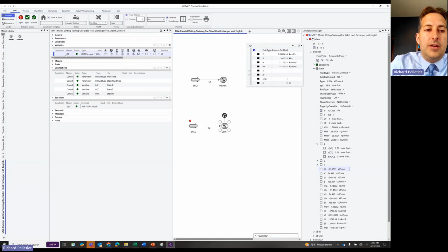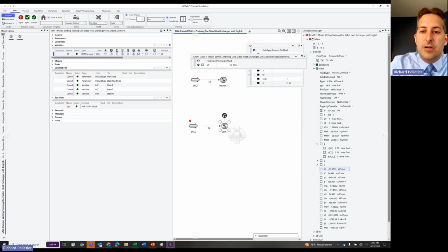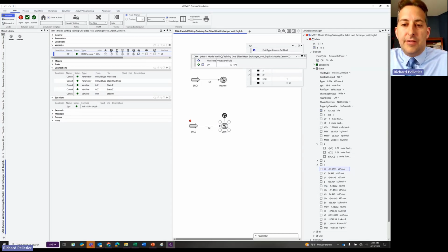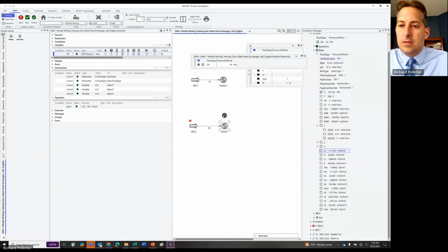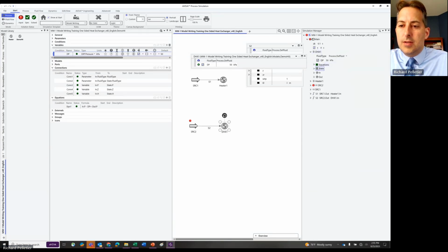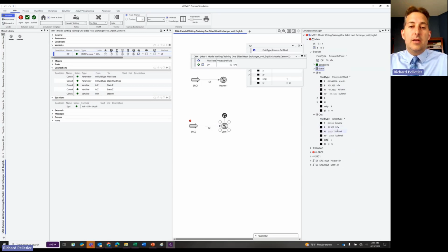So now I have the pressure drop implemented. If I look at this, you can see it's specified by default. Let's check and make sure that everything is working correctly, right? So I have a feed pressure coming in. It's 101.325 kPa. I have a pressure drop of 50 kPa. My outlet shows 51.32 kPa. Great. My pressure drop is working correctly. I'm done. Or am I?